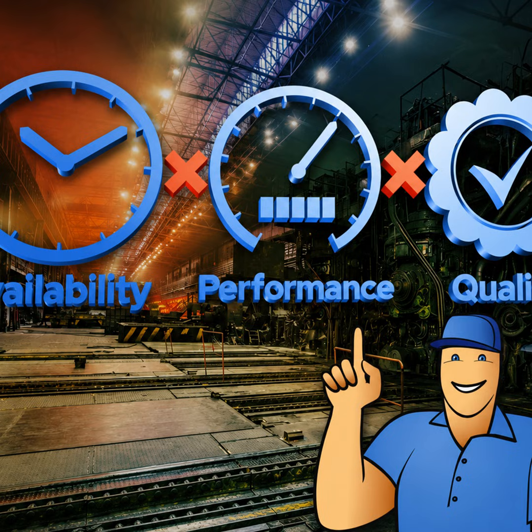Quality calculation. The last factor to analyze is quality. This is where you find out whether the products meet your quality standards. Let's say that out of the 204 units produced, 196 passed quality control inspection, while 8 parts had defects or needed rework. Here's the math. Quality equals good parts divided by total parts. In this example, that means 196 divided by 204, which equals 96.1%.